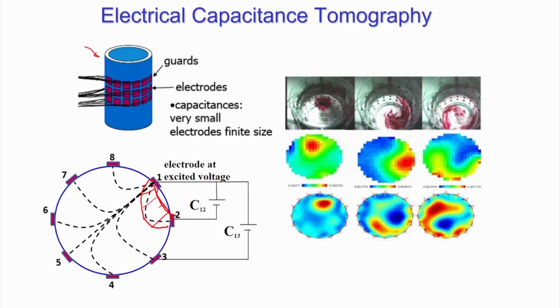And then for solving all these equations together, we will get the pixel-wise distribution of the fraction. So, suppose this is the one you got, let us assume that these are the electrodes. So the first electrode gives this information, the second electrode once you excite it gives this information, the third electrode gives this information, and the fourth again gives certain information. So, what will happen if you solve all this, you will get the pixel-wise information, that what is the fraction here, and because it is a non-linear path, the spatial resolution may not be very accurate. And that is what is being shown in this example.